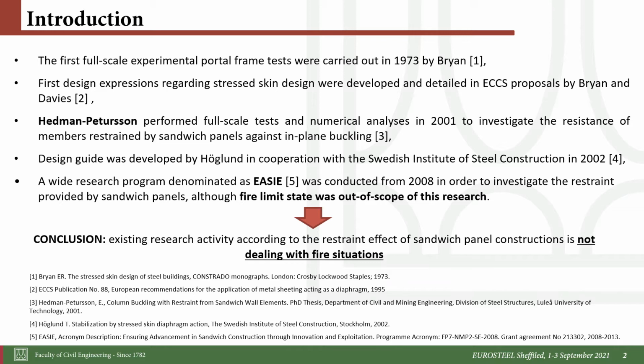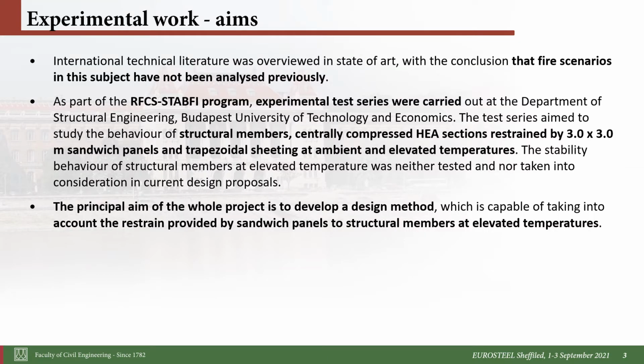There were some experimental tests in the so-called EASY project, but now our scope was to define the effect of the elevated temperature on the buckling of steel members supported by sandwich panels.